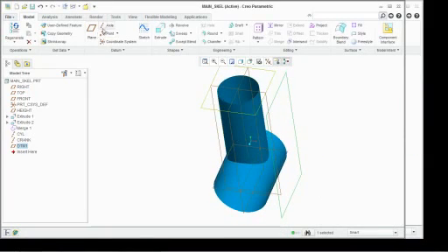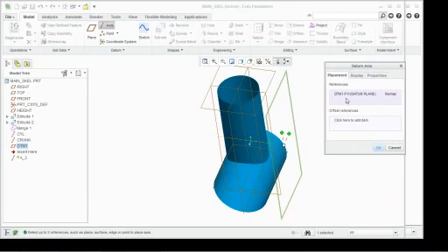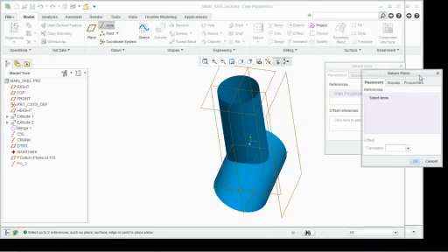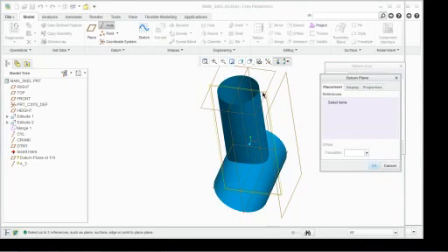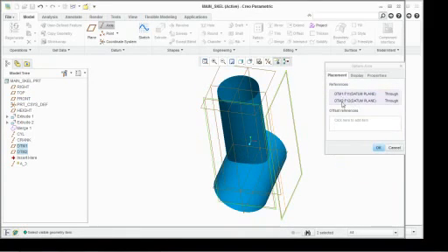And then I'm going to create an axis. With the datum axis tool selected, notice it did select datum plane 1 already. I'm going to select a plane tool on top of that. I'm going to pick this front plane and offset that 20 in that direction. Or no, this is the one that's supposed to be 10 here. When I click OK, it brings that plane, datum plane 1 and datum plane 2, both into the axis.